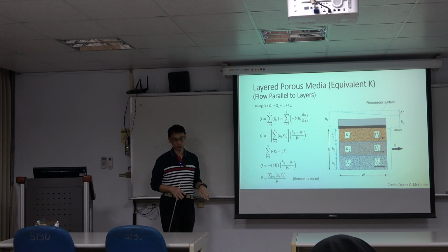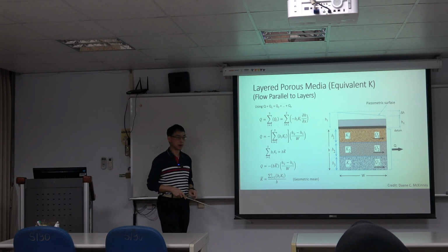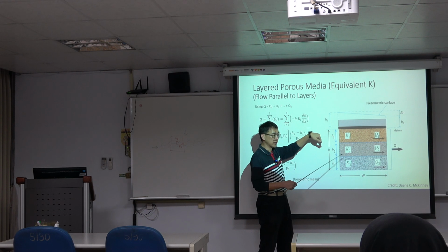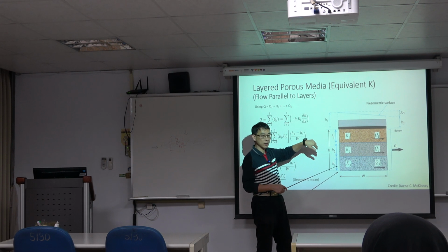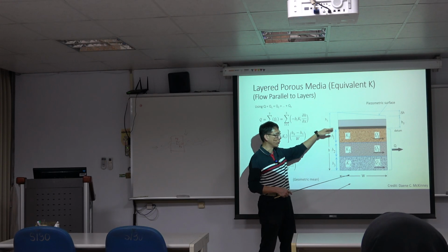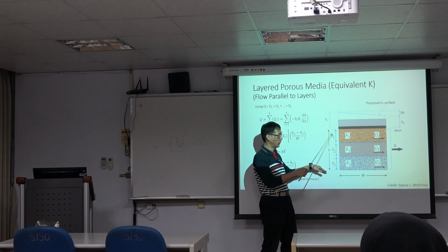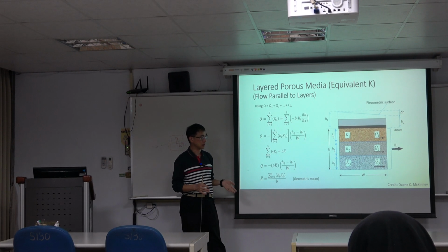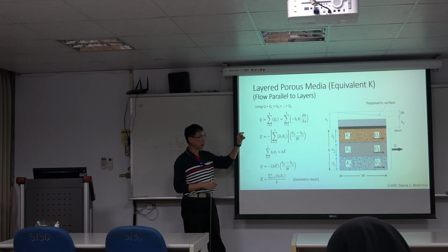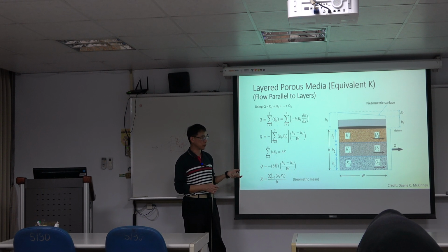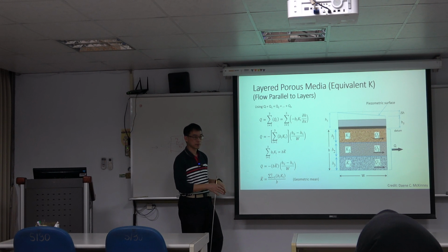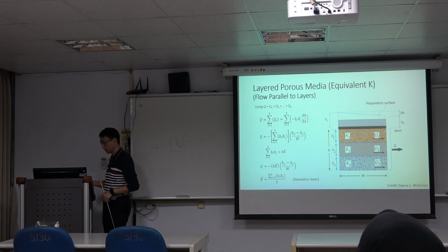Okay, so this kind of concept is also very important. As I mentioned, when we do the pumping test, commonly like this, we get the intervals. So we get the equivalent T values. We have transmissivity, but that's the equivalent for the aquifer system. And if you have different kinds of material, you will be able to calculate the equivalent quantity. But honestly speaking, it's also not easy because we are not able to have precisely the K for different depths. But you are able to imagine that if you have gravels in that interval, your gravel will be dominant. You become like you get the high K value or high T value.